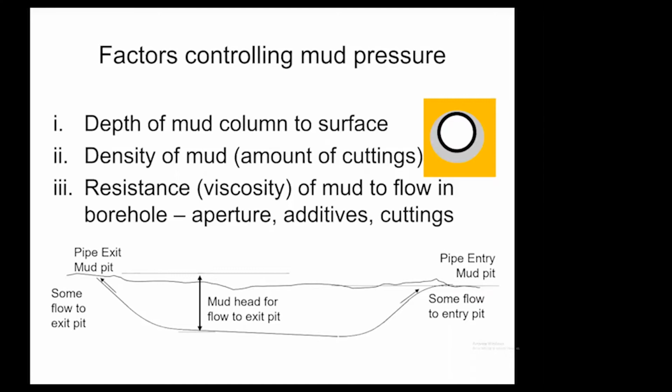First of all, we've got a column of fluid, that's the drilling mud, that's extending along that borehole up to the surface. So you can think of a hydrostatic pressure, which is just the unit weight of that fluid times the depth of that particular point, whatever point you're interested in, below the ground surface. So it's a height of column of mud producing pressure.